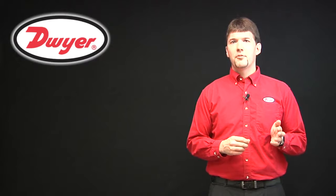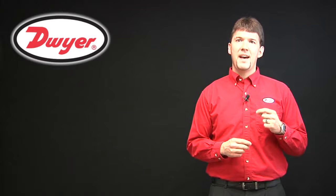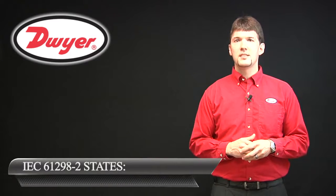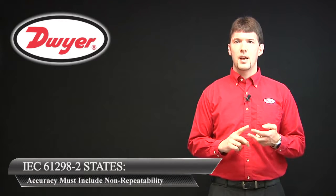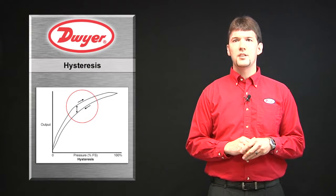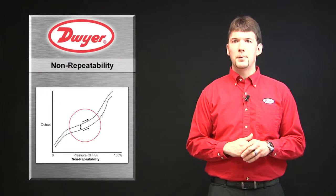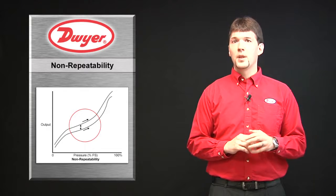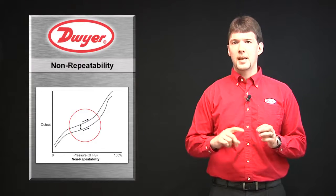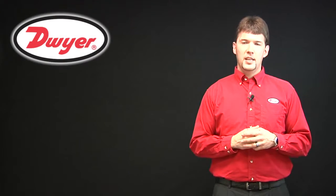Even though there isn't a defined standard for pressure sensor accuracy, there is an IEC standard that defines the factors that make up accuracy. IEC 61298-2 states that accuracy must include hysteresis, non-repeatability, and nonlinearity. Hysteresis is the maximum difference in the output between consecutive increasing and decreasing cycles. Non-repeatability is the maximum difference in the output when the same pressure is applied consecutively under the same conditions approaching from the same direction. Where manufacturers start to differentiate is with nonlinearity.